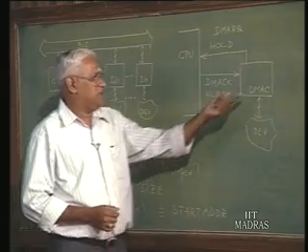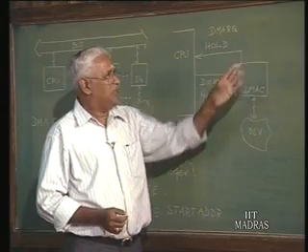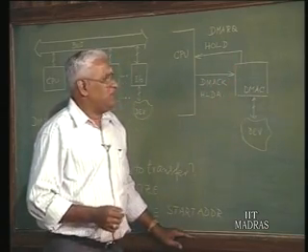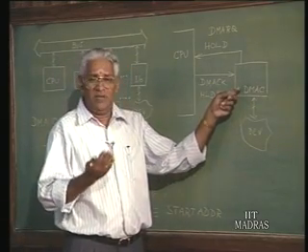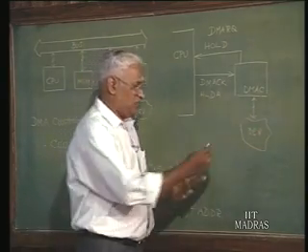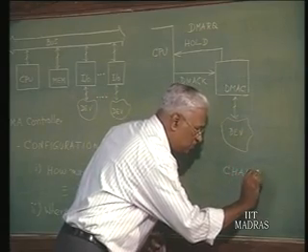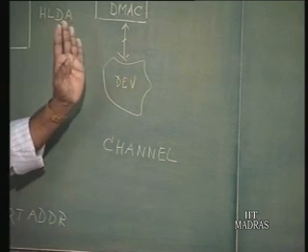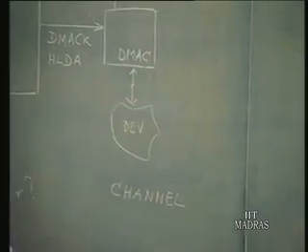For instance, now we know that like in any other interface chip, this controller will have a command register, status register, and so on and so forth, and then there may be other things. For instance, we have commercially available DMA controller chips which can take care of 4 devices at a time. Generally those things will be called channels, that is 4 channels, okay. We talk about a 4 channel DMA controller. That means I have just shown one device here, instead there will be 4, right.